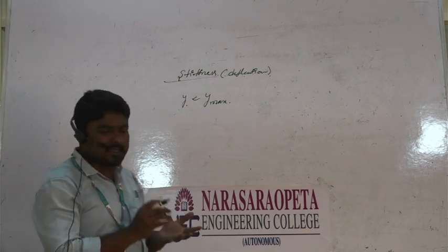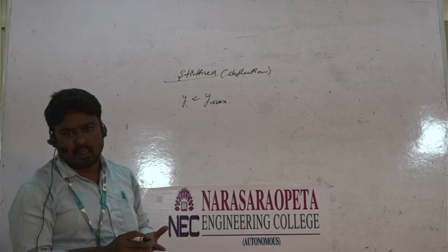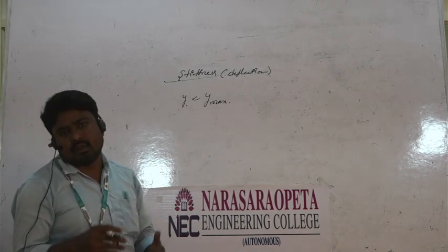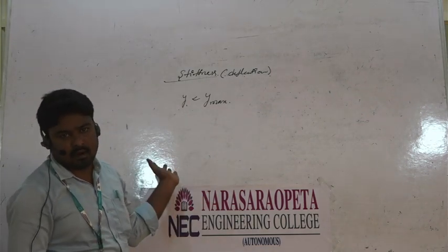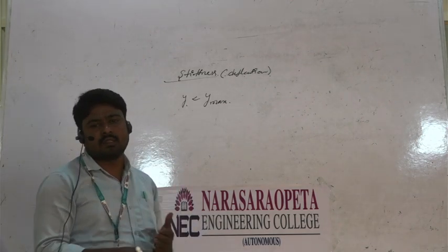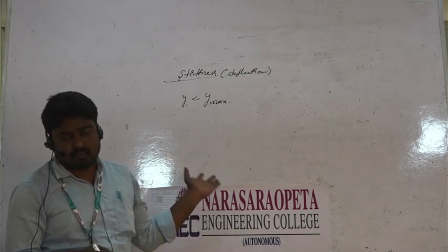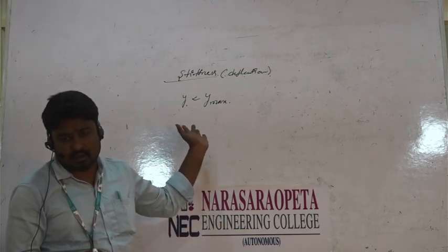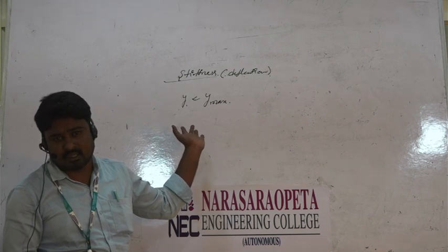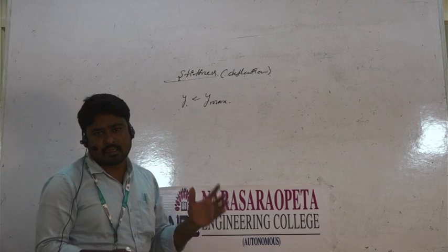That means for all these three requirements, strength, stiffness, and stability, we find separately with different equations, as we already discussed. Stresses are of different types: axial, bending, shear. We use the equations for axial stress, bending stress, and shear stress. We find the stresses, and if these stresses are within the limit, it has good strength.